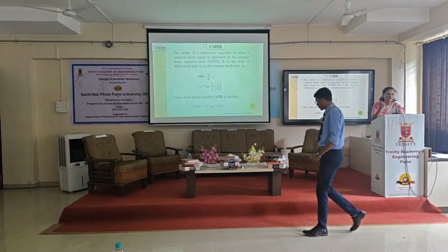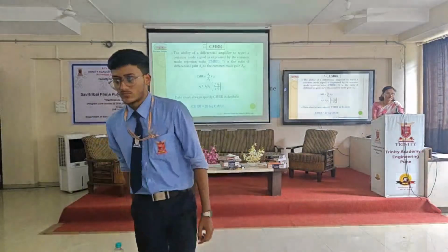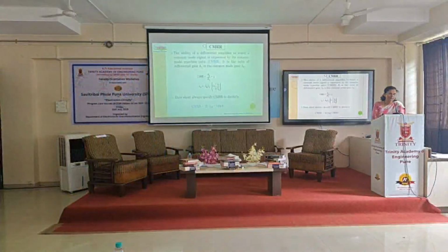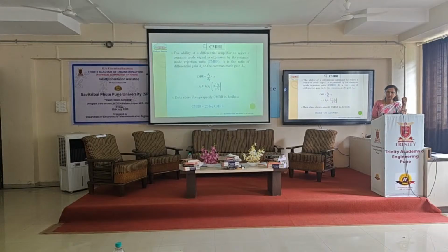But if you go through all these parameters, some parameters are coming under the DC characteristic and some are coming under the AC characteristic. Okay, the next one is coming in the syllabus. In that, out of all these parameters, two parameters you have to consider under the AC. For example, gain bandwidth product and slew rate, these are coming under the AC.